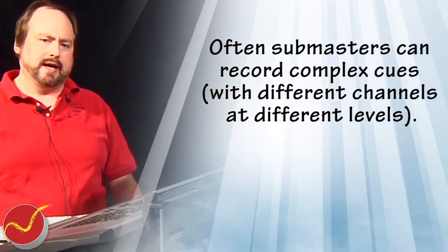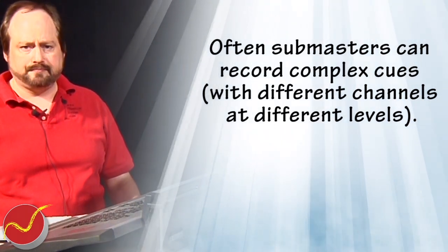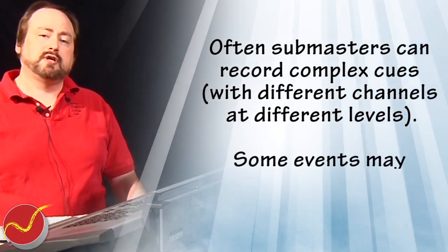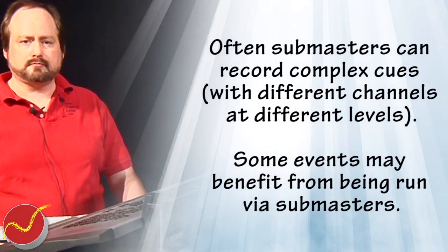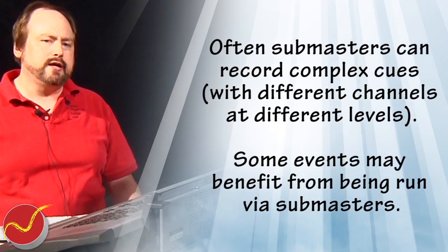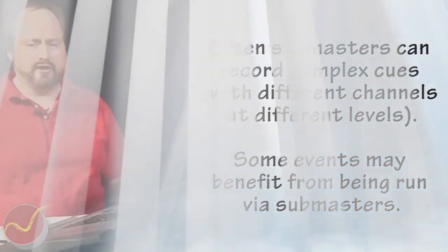We were using Submasters to group a bunch of channels together, all at the same level. We can also record more complex cues into Submasters, and oftentimes it may be easier to run an event using just the Submasters. For example, an award ceremony or lecture presentation. This will allow you to quickly adjust the lights to follow the unpredictable nature of those events.